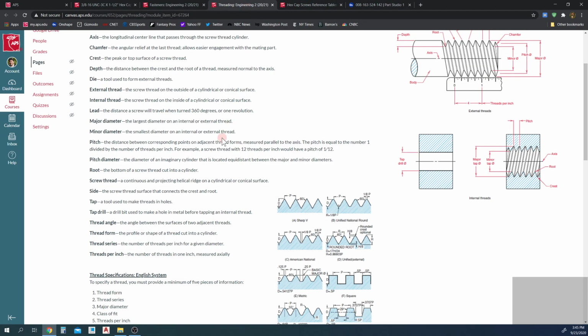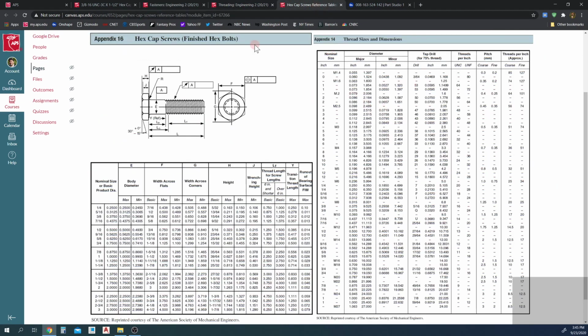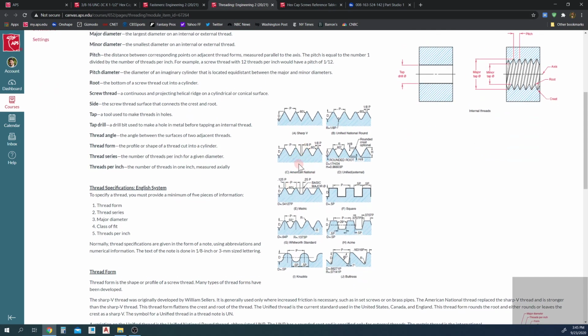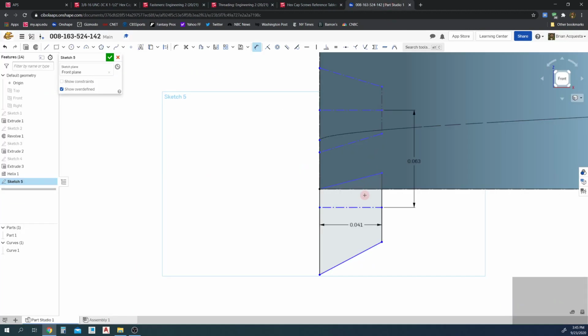I know that, excuse me, I need to go. Where do I need to go? I need to go threading. Here we go. The bottom is 1/8 of an inch, 1/8 times by the pitch. That bottom, 1/8 of an inch times by the pitch. So from here to here. So let's put that distance in. So from here to here, 1 divided by 8 times by the pitch, 1 divided by 16. And using parentheses, order of operations.